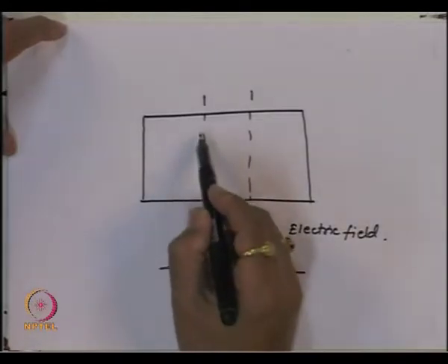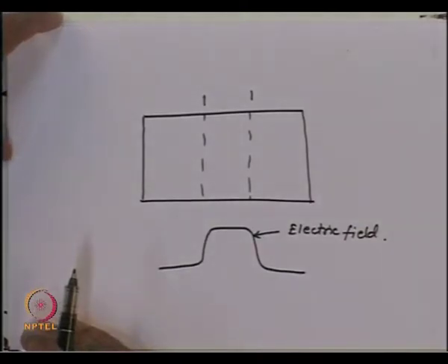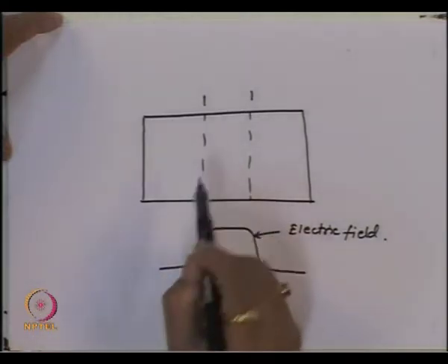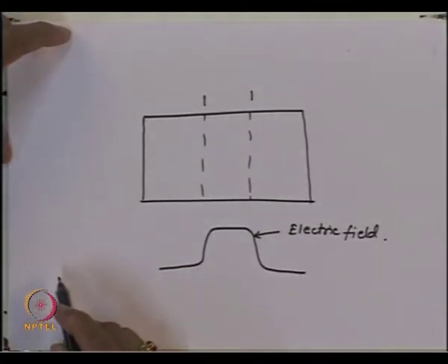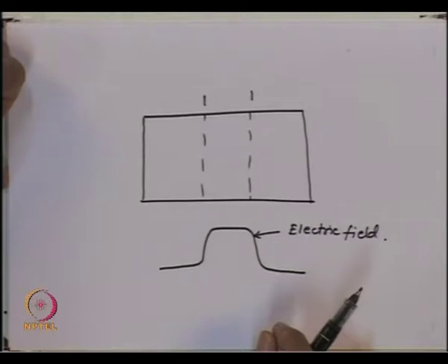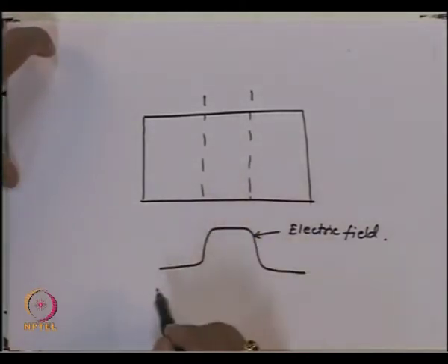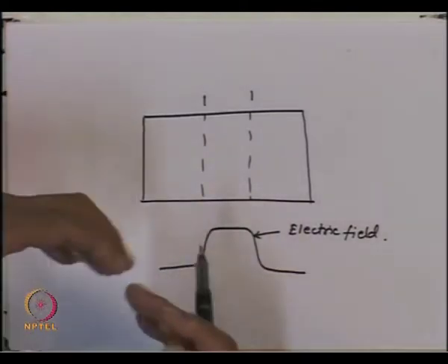So, most of the photon absorption will take place outside the depletion region. So, what that means is that if you take a typical simple PN junction, then the diffusion current is the one which will be more dominant compared to the drift current, and as a result this device response will be very slow.